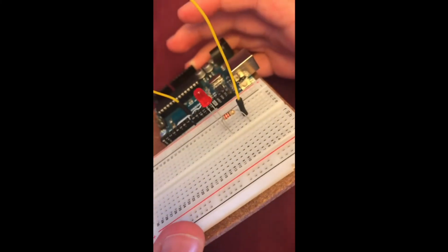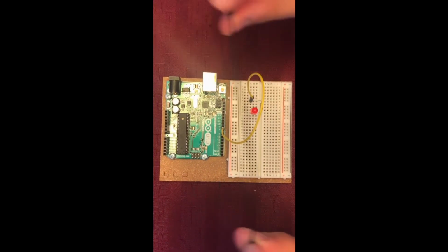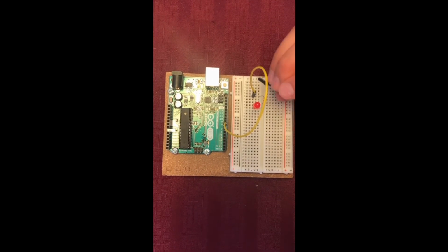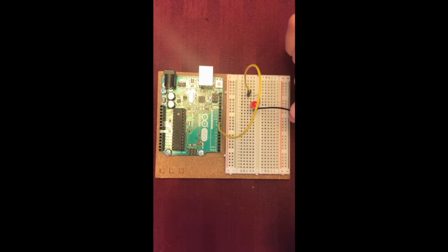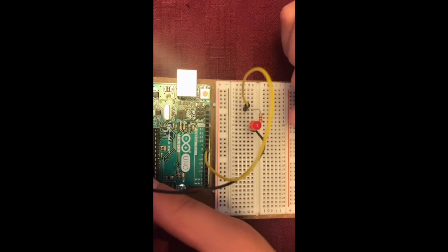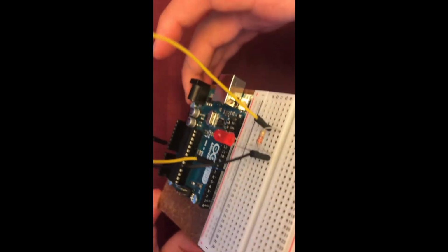So this is how it looks like right now. And then take the other pin, and this one is very simple. So connect it to this, which is the smaller leg of the LED. And then this one connected to GND, or ground. And that's it. That's pretty much it. So let me show you. This one is connected to ground, as you can see. There's 2 pin grounds, and then this one is connected to pin 8.